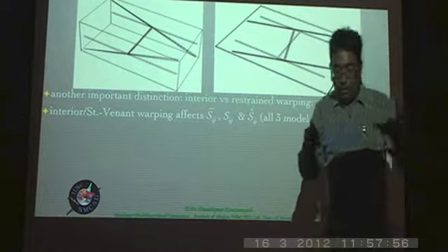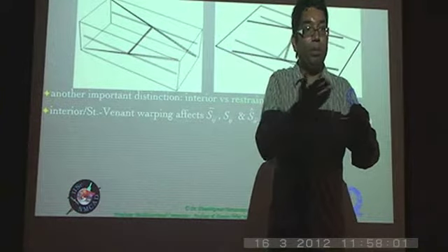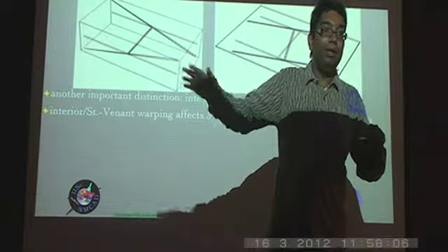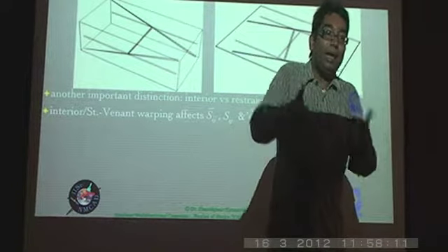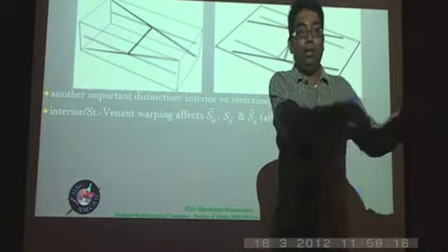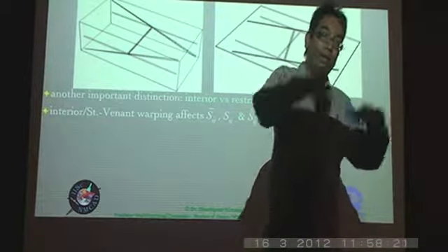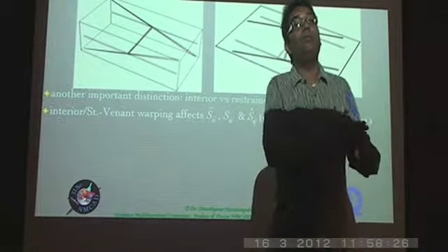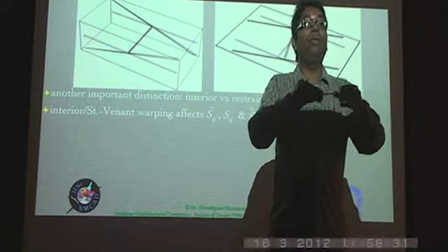See, warping is basically defined as the motion of the particles over and above the average motions of the cross section itself. So that's basically warping. Now the source of that, what is actually forcing that to come into picture, into it being non-zero, is basically the 1D measures. If it happens to be not just the 1D measures but their derivatives like kappa 1 prime, then it's basically a restrained warping contribution, something which has to deal with basically how the boundary conditions for the beam itself are.